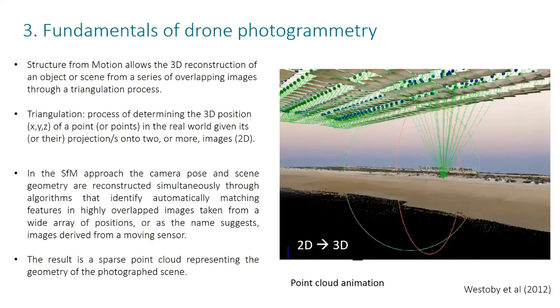And how do we obtain high resolution topography of the coast? First, of course, you need a drone that is equipped with a camera. But you also need some specialized software to process all the images that are captured by the drone. And this software works with what are called structure from motion algorithms. In my opinion, drones have become really famous tools, of course, because of the potential they have. But for me, another impressive thing is what these structure from motion algorithms can do in this software.